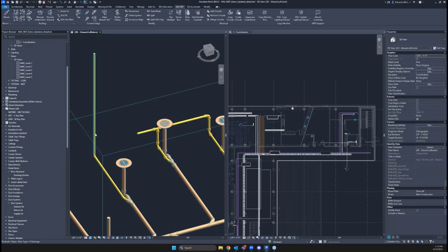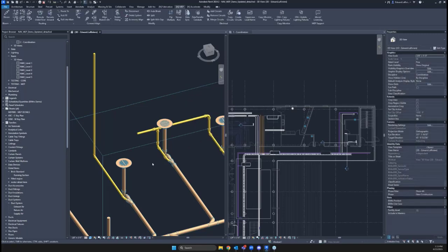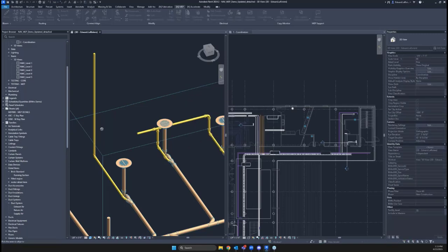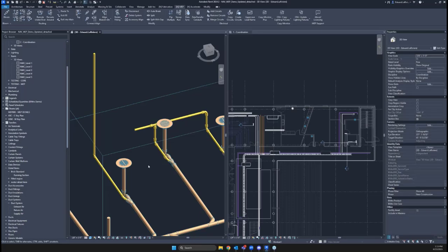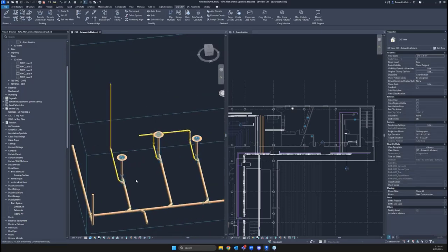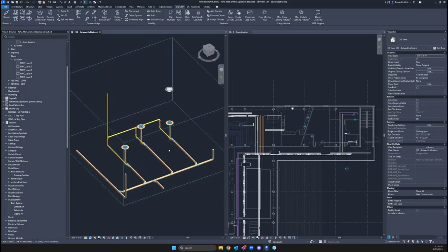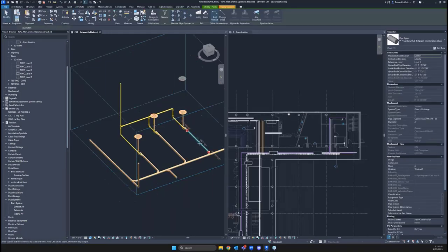Now I need this to line up against that vertical, and that Align Branch is not just for slope pipe, it's for any time you want some stuff to be lined up together, except for this one. Oh, there we go, perfectly lined up for us to then do a Trim Extend again and get that perfect connection. So the name of the game is small automations linked together that let us do something a lot more advanced.